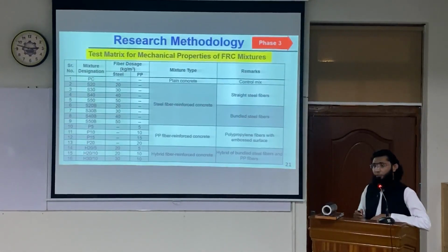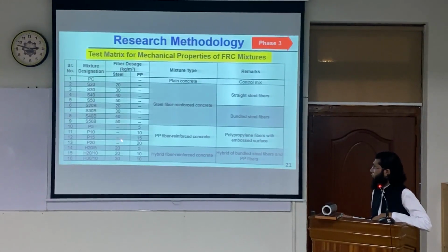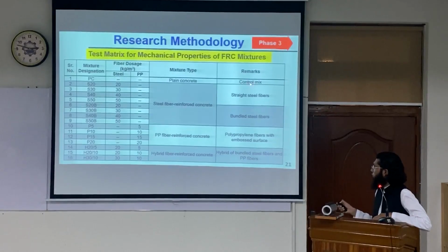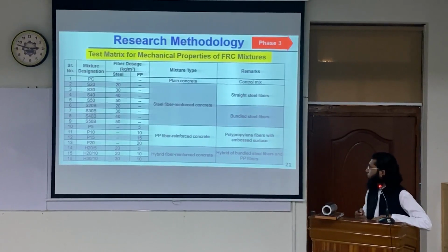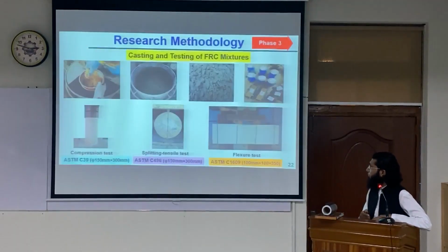So this is the test matrix for exploring the mechanical properties of various fiber-reinforced concrete mixes. A total of 16 different mixes, with control mixes of plain concrete, straight steel fibers, bundled steel fibers, PP fibers, and a hybrid of bundled and PP fibers at various dosages.